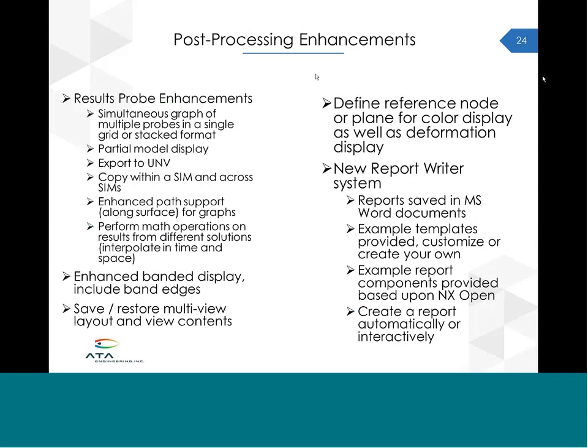Now that covers a wide variety of pre-processing enhancements. There have also been a number of post-processing enhancements as well. In particular, related to the results probe, there have been a number of enhancements. In particular, you can simultaneously graph multiple probes in a single grid or a stacked format. You can restrict the display to just a portion of the model. You can export result probes to a universal file.